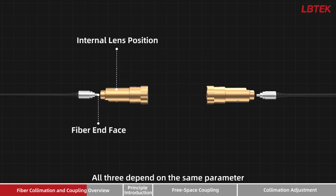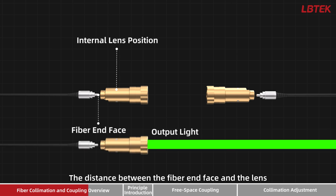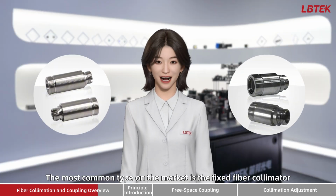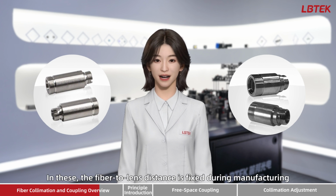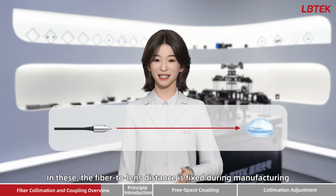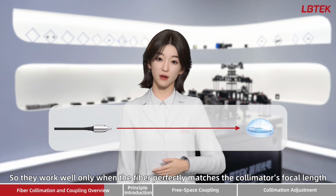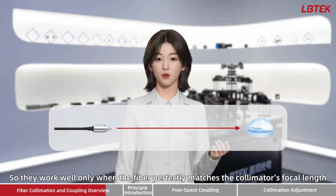All three depend on the same parameter: the distance between the fiber end face and the lens. That distance determines, for collimation, how parallel the output beam is, and for coupling, how efficient the launch is. The most common type on the market is the fixed fiber collimator. In these, the fiber to lens distance is fixed during manufacturing, so they work well only when the fiber perfectly matches the collimator's focal length.